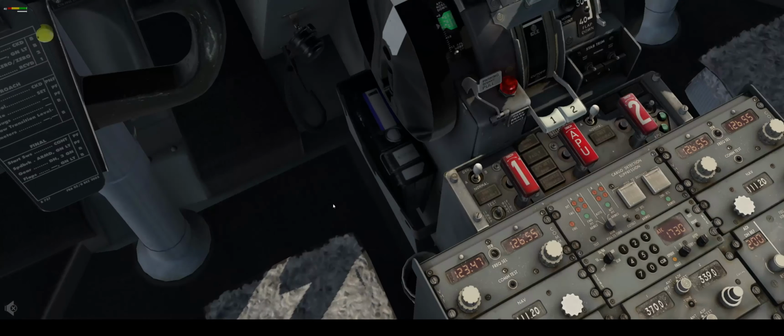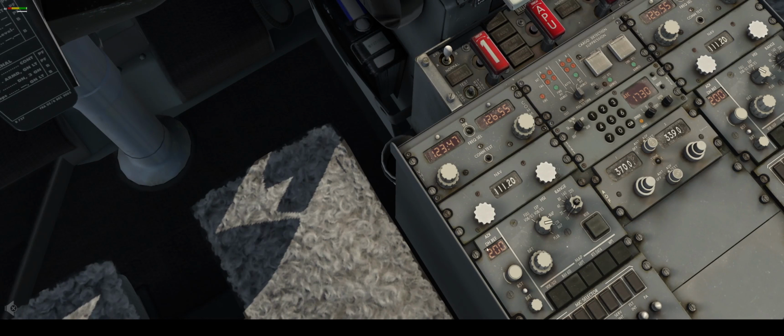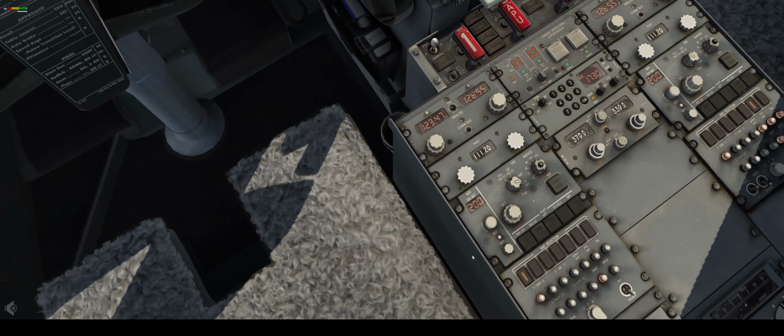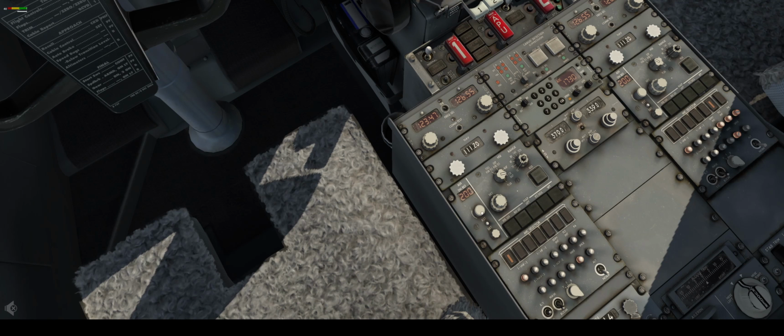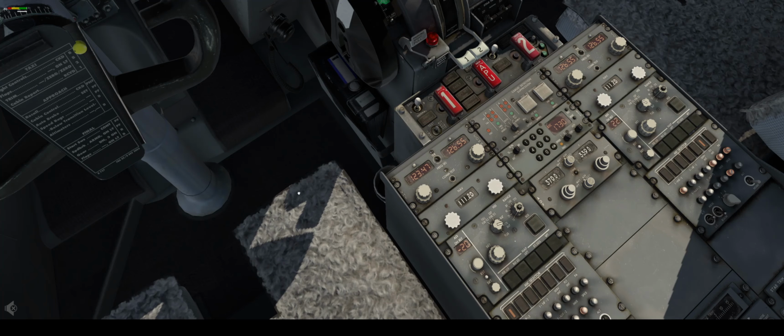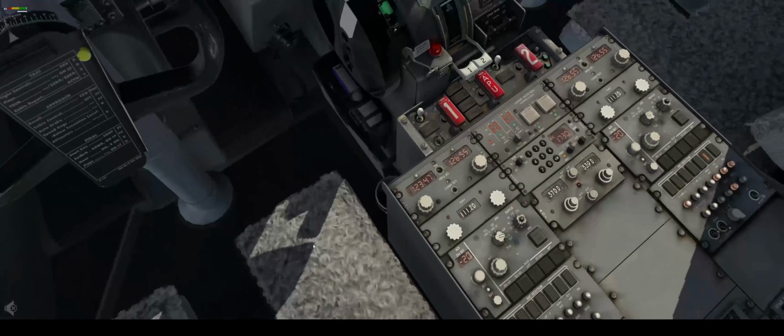I will not discuss. This switch is decision height, so that means that it has something in common with low visibility procedure and autoland. So you adjust it and put the decision height only if you are making an autoland. Okay, and you can put the decision height, for example, for CAT 2 100, for CAT 3 50 feet. Okay, but if you are within pre-flight procedure, you have to put it into -20 in order to get rid of the wrong callout after departure.